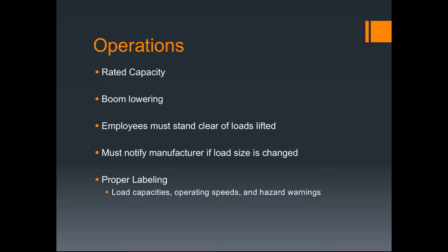And when moving a crane around a job site or construction site, you just need to make sure that the boom is lowered, because this is just another safety precaution. If the boom is up, there's a greater chance for an accident to occur on site. And employees must always know when a crane is moving and must stand clear of the loads lifted. When the crane is in use, they need to make sure that they're not around that area, because if anything falls from the crane and employees are standing below, that would be a very dangerous situation. It's sad to say, but that's how many accidents happen with cranes, from falls. About 20% actually happen because of that.